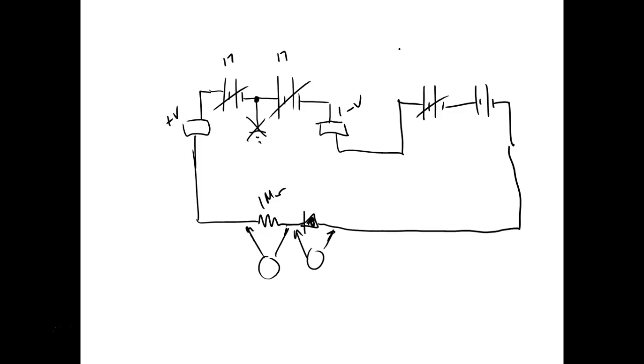But even though it breaks over, guys, you know, we're limiting our current with a what? With a 1 mega ohm resistor. So if that 1 mega ohm resistor wasn't in there and I broke it over, that diode would be gone just like that. But here we're going to break it over with that big resistor. And that's why we have problems with our power supplies: your diodes are unprotected. They don't have a big resistor in series with them. We're hooking them up directly to the what? To the transformer. And all we're dealing with is the R of the transformer, and the R of the transformer has nothing, right? You understand that?